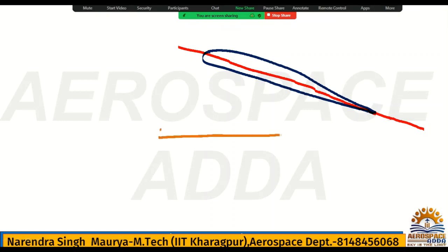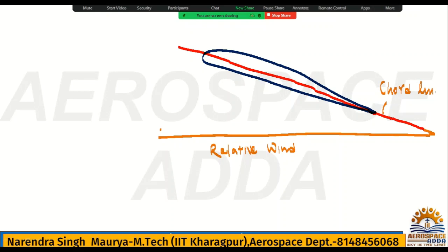So we just say this is the relative wind. What is it called? Relative wind. And this is what? Chord line. The angle between chord line and relative wind is nothing but alpha. What is alpha? Alpha is the angle of attack. Now here we have a flow velocity, free stream air, which is nothing but V infinity.